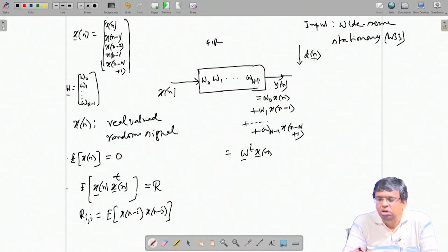given to you, and during that time we call it training time, adaptation time, adjustment time. During that, using the given d n, you adapt the coefficients to become a better filter, or whatever be the best filter required currently under the current circumstances. I mean adjust them, adapt them by some formula, clock by clock, iteratively during that window.